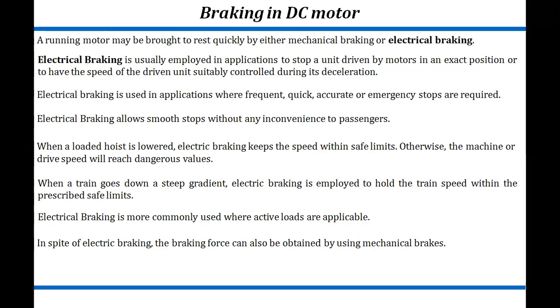Then we have seen the construction of DC motor and DC generator. Both have the same general construction because both have pole and yoke as a stator, which will not rotate and remains the stationary part. And the armature winding, commutator, and brushes are the rotor of the DC machines, which will rotate when we give the power supply.